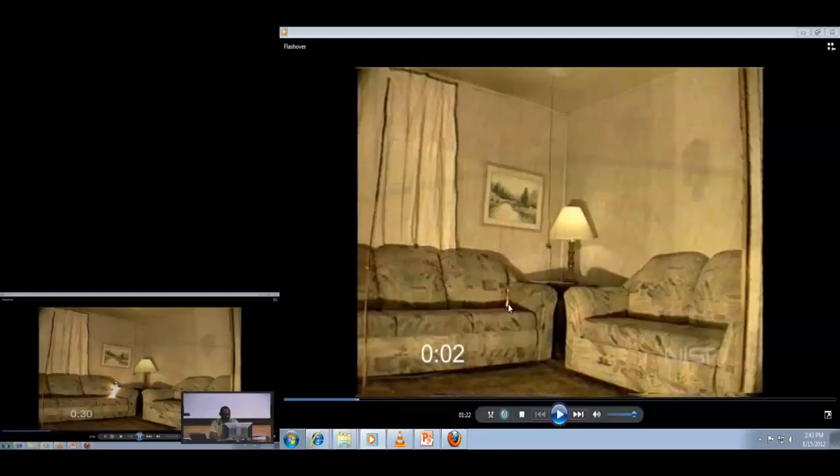The soot particles that are formed within it actually pop out. They're not oxidized, and they continue to evolve and grow as they go up. Now, if there had been a smoke detector here, we imagine that smoke detector would have alarmed probably around now, because on the order of a 100 kilowatt fire for a room of this size would likely cause enough particles to be lofted to start a smoke detector. A 100 kilowatt fire is like the fire that you might have in a waste paper basket.